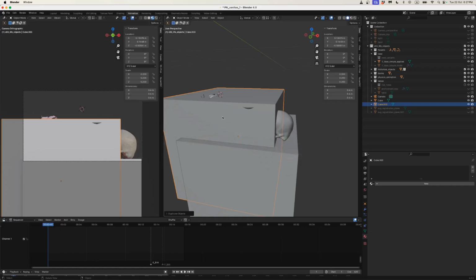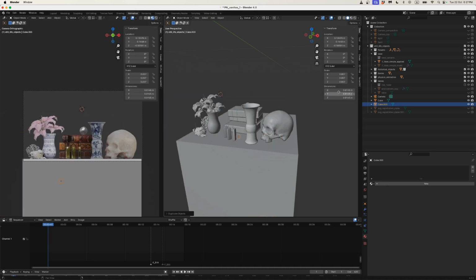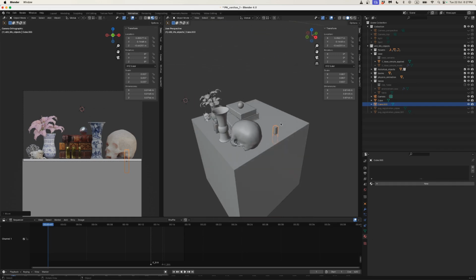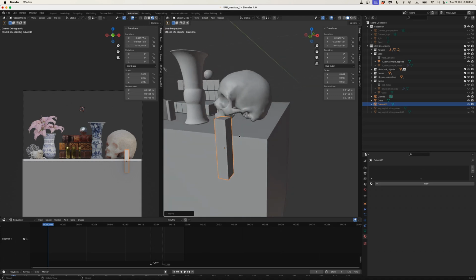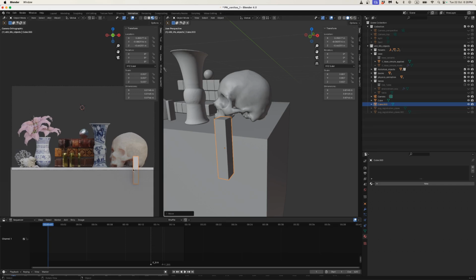So let's pop into Blender, and I'm going to make this 14.5, so that'll be 0.0145. Looks really tiny, and then scale it on the height axis a bit, bring it up. I'm going to bring them right forward so we can see what we're doing. They can be in front because we have no scaling in orthographic, so it doesn't matter where we put it, we just want to see it. The other thing is we don't want it to be too long, but it needs to be at least the thickness of our wood. Our wood is 3 millimeters. So I'm going to turn on my snapping and snap to edge, and bring this up.